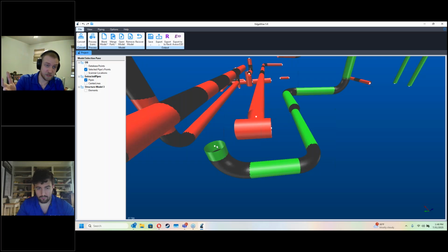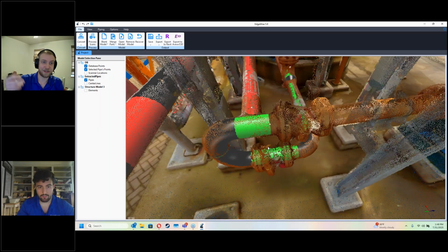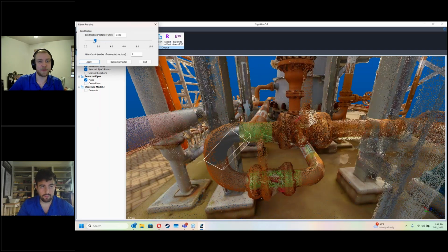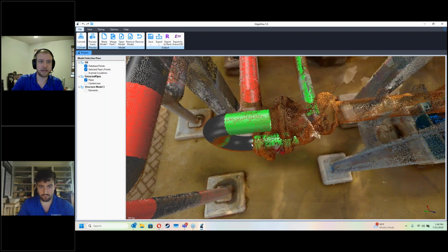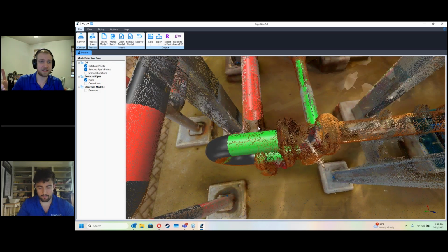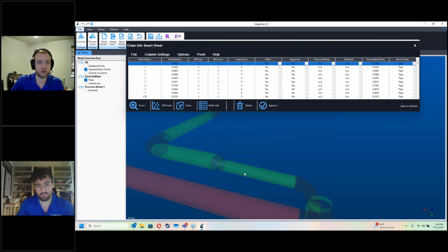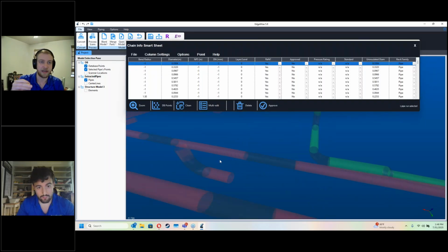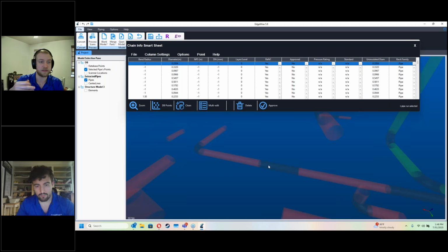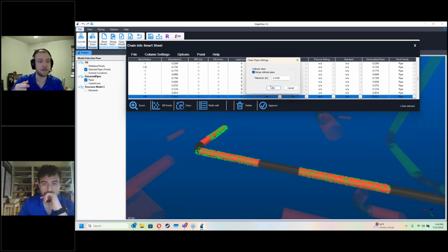That goes for system type. If you forget to set the system type and you wish this was a duct and not a conduit element, delete just that inside of Revit or whatever you're working in, set that system type inside of EdgeWise, select that and export only that, and then suddenly you don't have to restart your whole modeling process. So that's a really important improvement in the workflow that's kind of easy to miss.